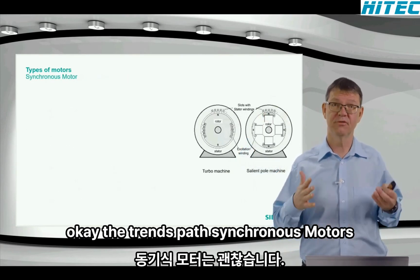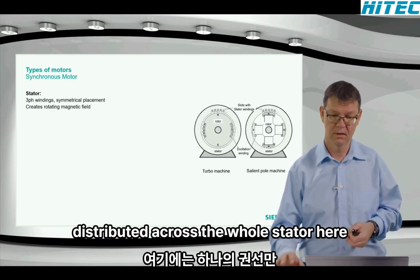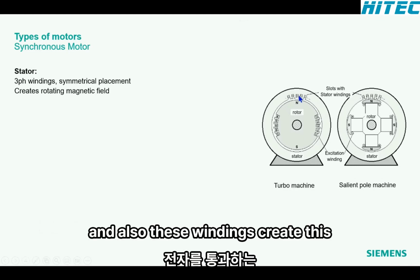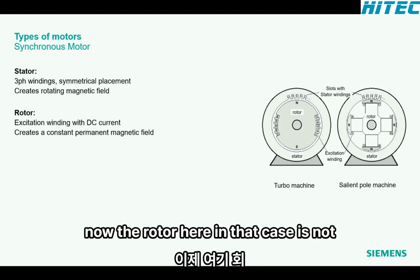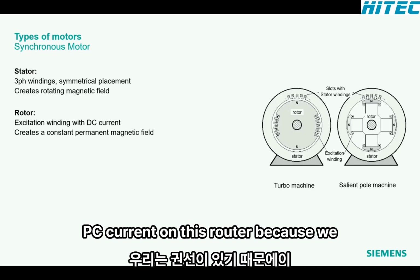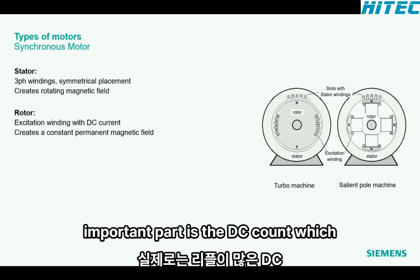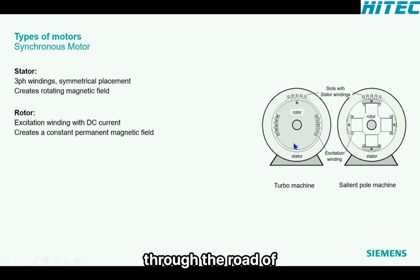Okay, the difference, we have synchronous motors. Also there we have a stator with the 3-phase windings distributed across the whole stator. Here just one winding is indicated, so you need to add the other windings for the other phases. And also these windings create this rotating field of the stator, which goes through the rotor. Now the rotor, in that case, is not powerless, let's say. So there is a power going in. We have a DC current on this rotor because we have a winding in the rotor, and here we inject a DC current. In reality, it's a DC current with a lot of ripples, but the important part is the DC current, which creates a permanent, more or less constant magnetic field, which goes through the rotor.